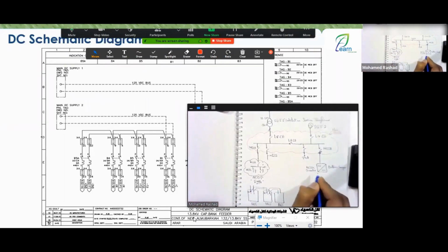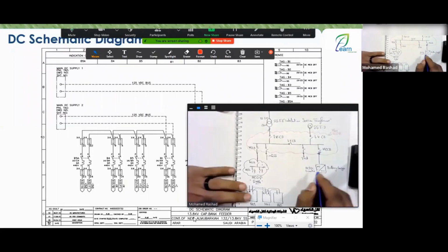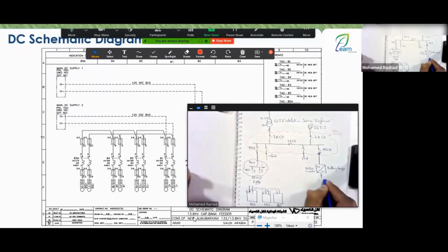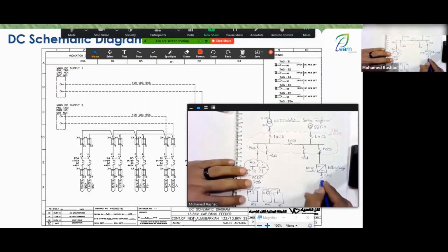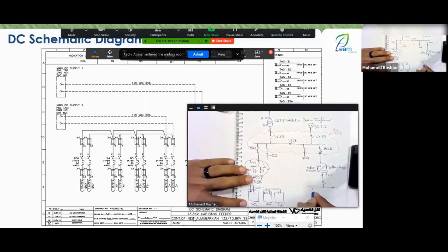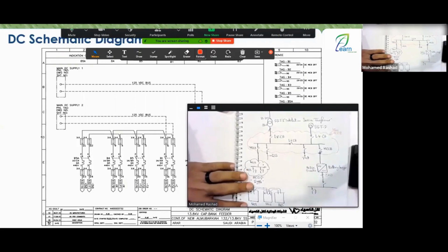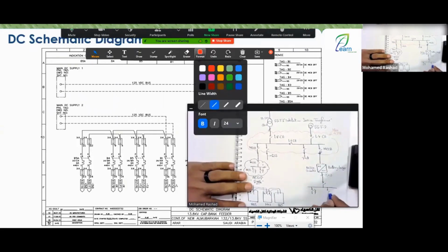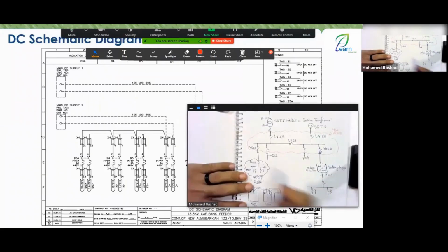Great, that's very nice. All right, continue with me. When you exit from this, of course, it will be positive and negative. These go here like this and enter here on the incomer, and then on the bus bar. And it starts to exit from this bus bar, possibly with a miniature circuit breaker, depending, of course, on the loads you have. It also exits like this with a miniature circuit breaker and so on. It exits with such MCBs or distributes depending on the loads present.